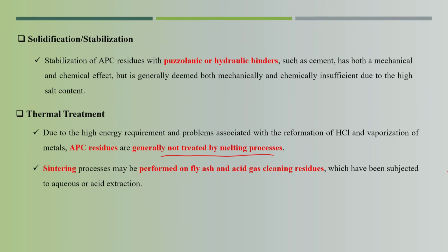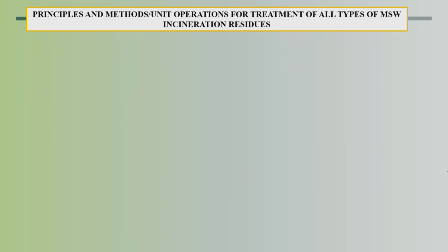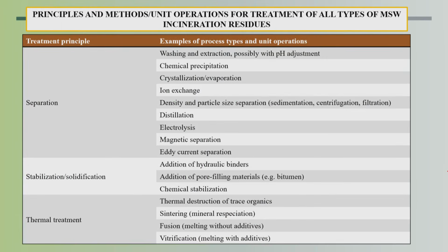Or similarly, the sintering process may be performed on materials which have been subjected to aqueous or acid extraction. Now, these are the principles and methods or unit operations for treatment of all types of MSW incineration residues. These are the three major principles we talked about: separation, stabilization or solidification, and thermal treatment.